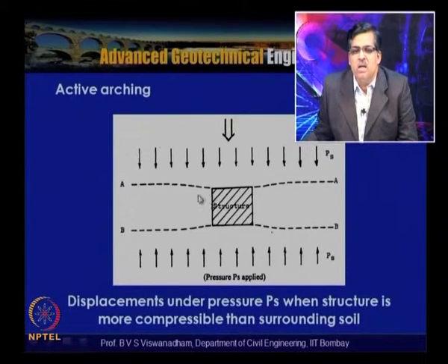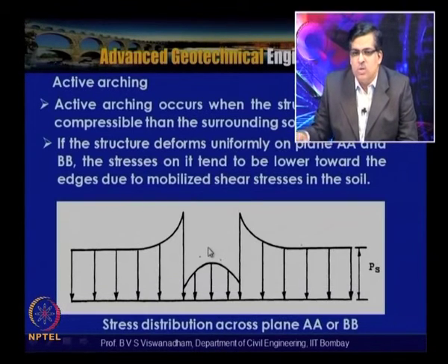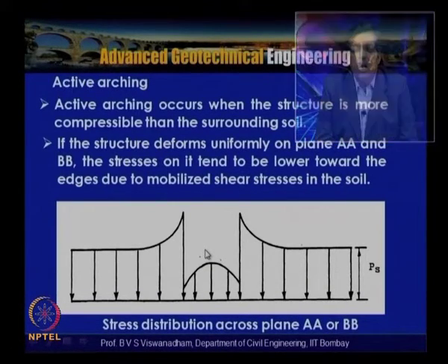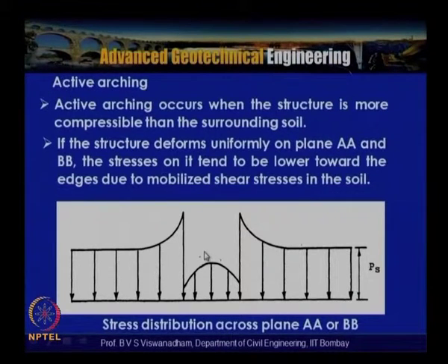You can see that the soil in this portion will undergo settlement, and so this is the displacement pattern under the pressure when the structure is more compressible than the surrounding soil. So in this case, active arching occurs when the structure is more compressible than the surrounding soil.